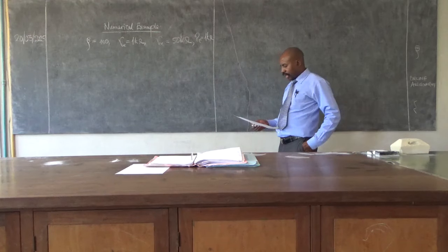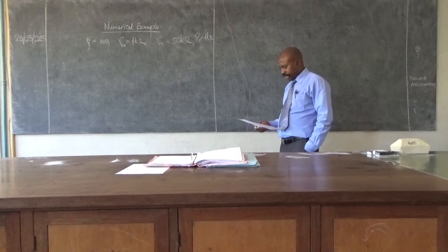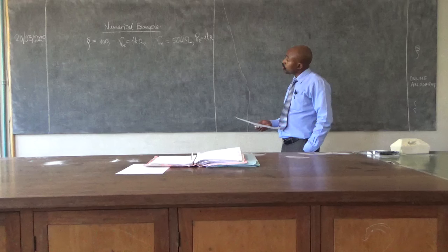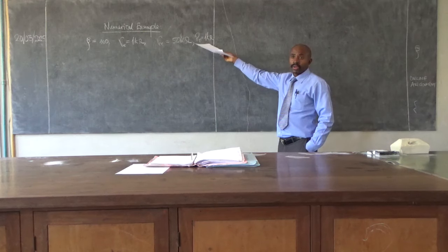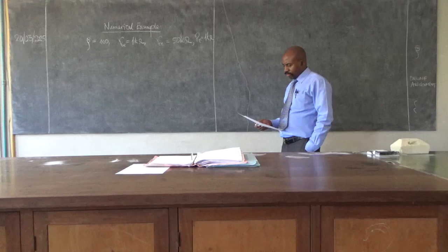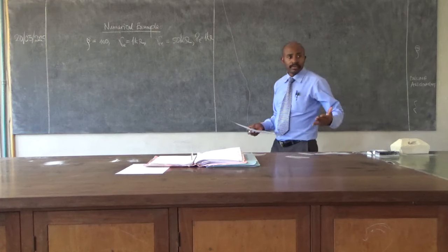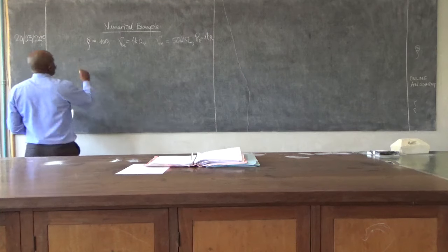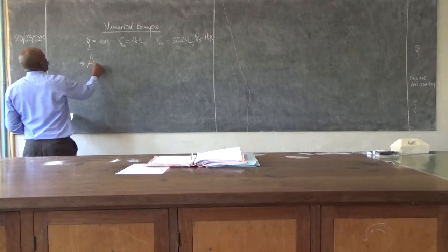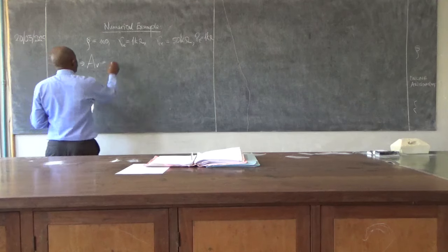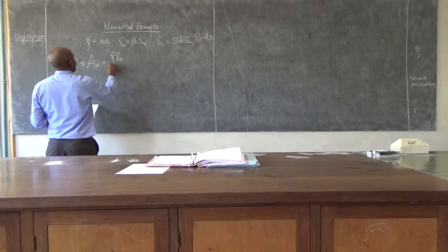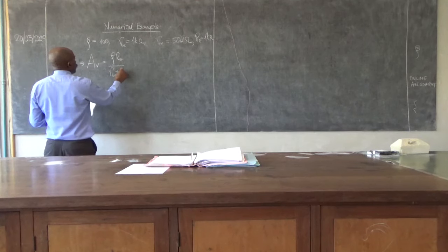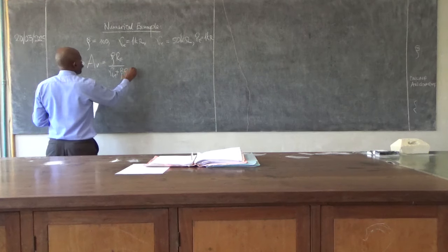And then we have RBE as 1K and RE being 1K, and of course beta being above 1, as in this example. So this would imply that our voltage amplification would be beta RE over RBE plus beta RE.